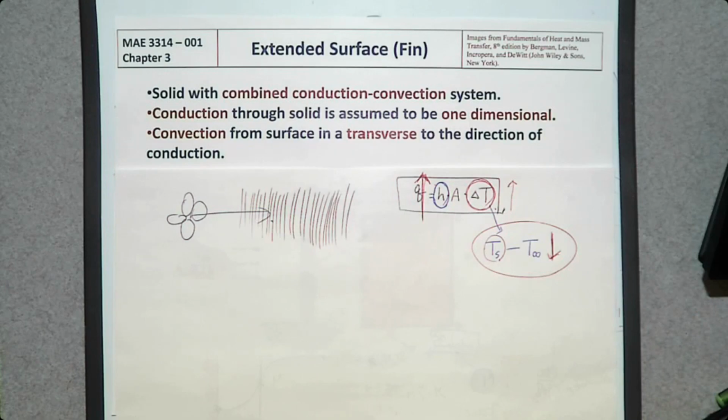Yeah, that's a good way. So if you stay in a parking lot, if you drive faster, of course, it increases the forced air velocity. So that will increase the h value. Okay, that can be one option. But we want to make sure that the engine is okay when it is idle in a parking lot, right?